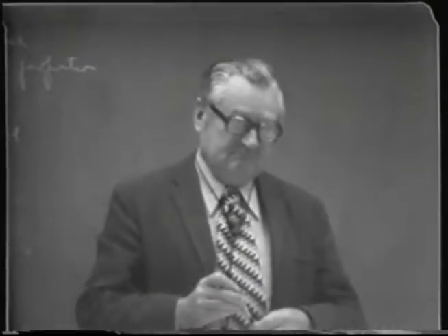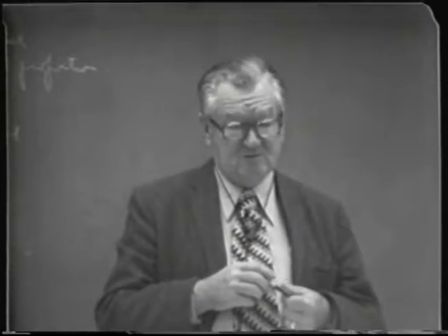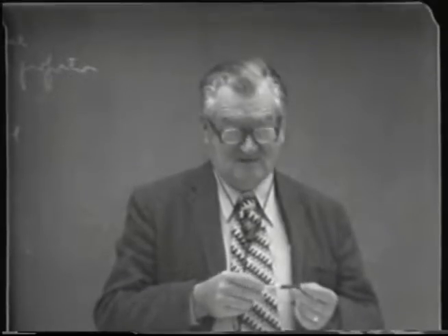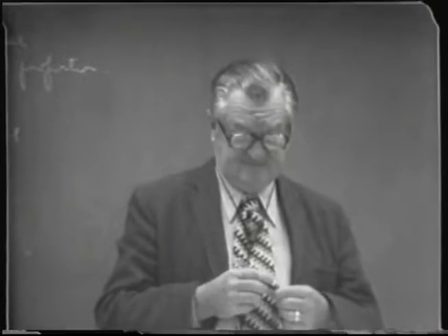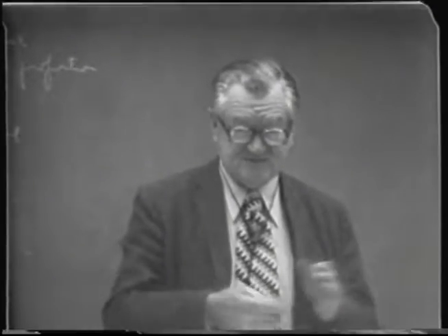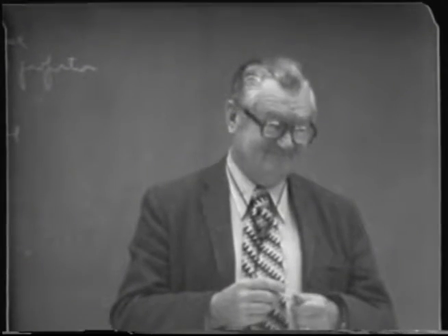What does this mean as far as the fate of acetic acid in the wine that's fed into a continuous distilling column? What will be its fate, assuming it's unchanged, assuming it's not esterified in the column? It'd go out in the bottoms, right?